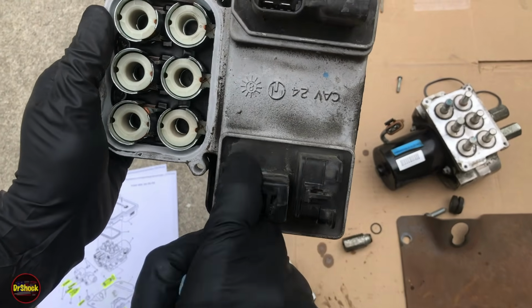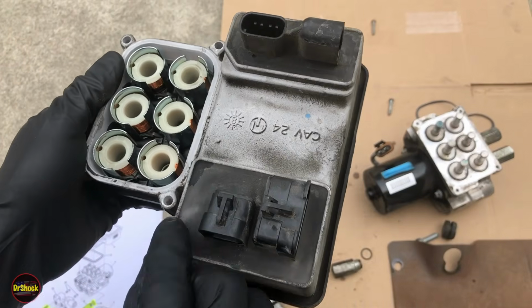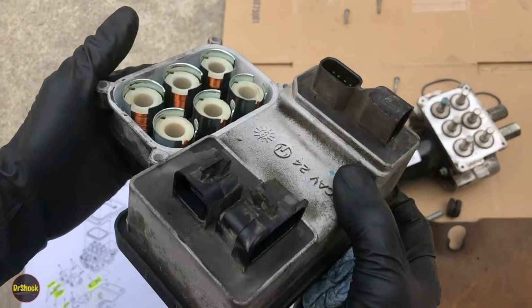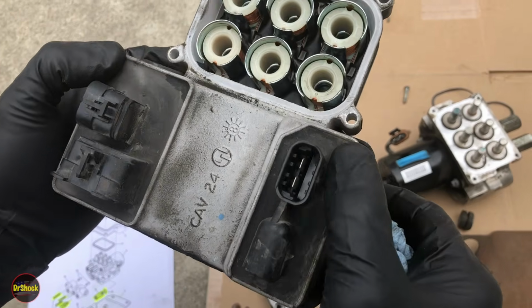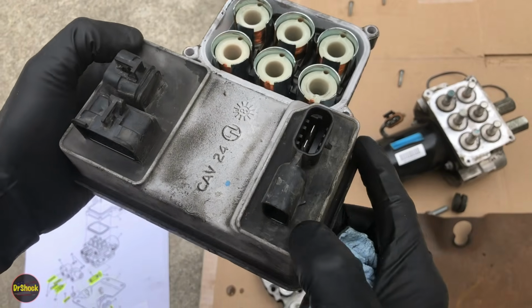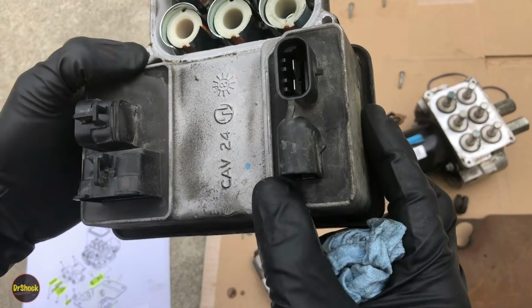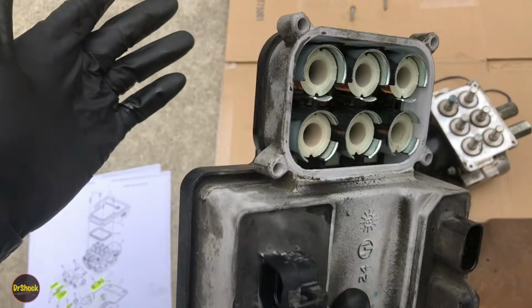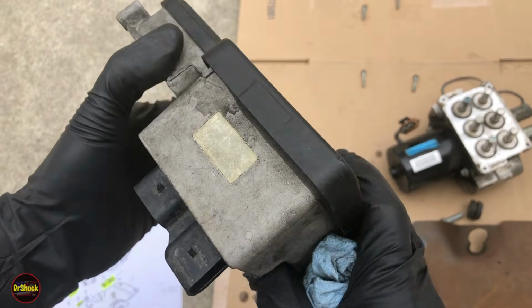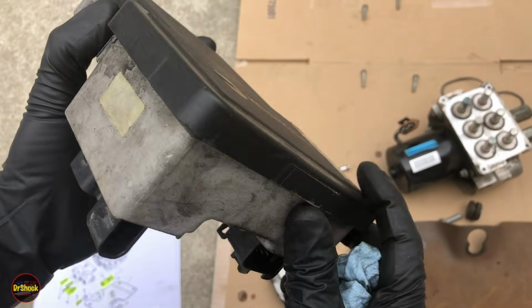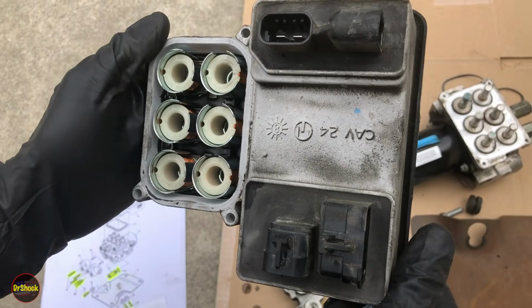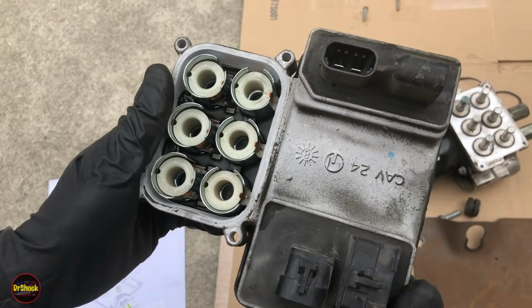We can see everything in here. The electronics has all been filled with a potting material. Those of you with a 6.5 liter diesel are going to be familiar with this from the pump mounted driver or the fuel solenoid driver. It's all sealed and encased in epoxy. You can't service the electronics inside. Nobody can rebuild these. The only way to get this thing open would be to tear it apart, and then it would not be waterproof anymore, so it can't be rebuilt.